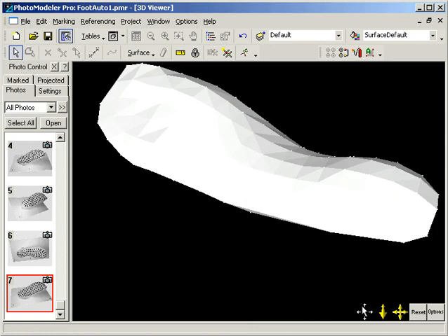We review our resulting triangular irregular network of points. We click on the surfaces to show that these are individual triangular surface elements. This surface project can be exported in its current state to any program that accepts these triangular elements. Another powerful feature that works well with dense point grids on a complex surface is the point cloud surface.